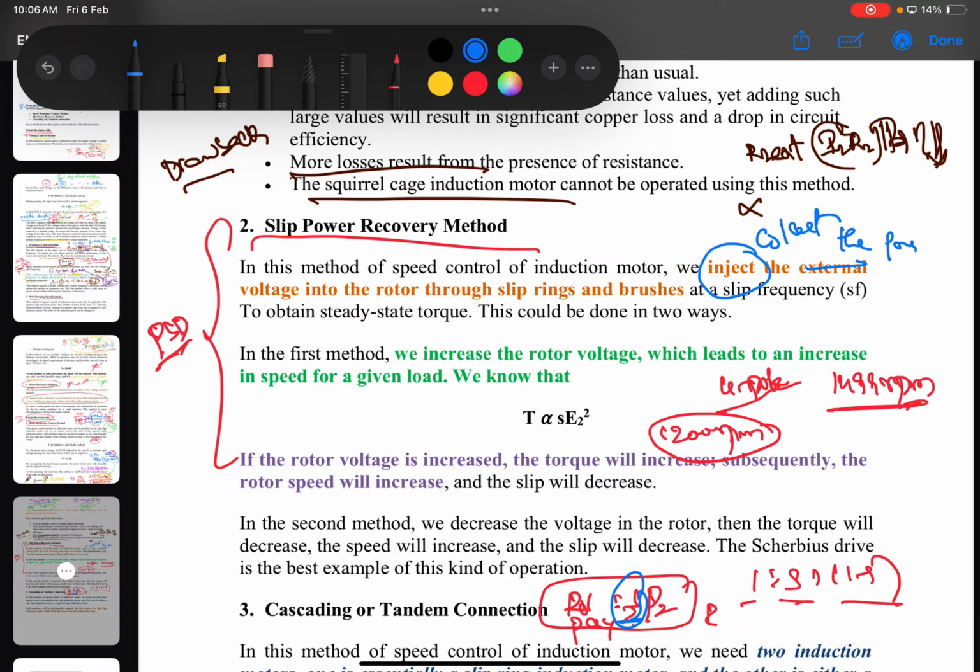Motor which is capable of operating at maximum speed. When it operates at lower speeds, other than the maximum speed, the remaining extra power which is capable of driving the motor to the maximum speed will be wasted in terms of rotor copper losses.